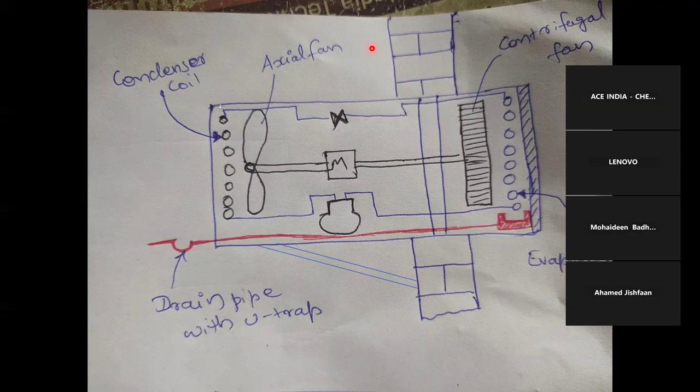Generally, in the case of a window AC, you will not have this kind of expansion valve. Instead of that, you will have capillary tubes. Why? Because I told you this window AC is meant to be a conventional type machine itself. Or in other words, this is the starting machine, the first machine that was implemented as a modern AC itself. So in these machines, you can only see capillary tubes. Before this capillary tube, you will have a small arrangement called a strainer. Okay, what is it? A strainer will be there.